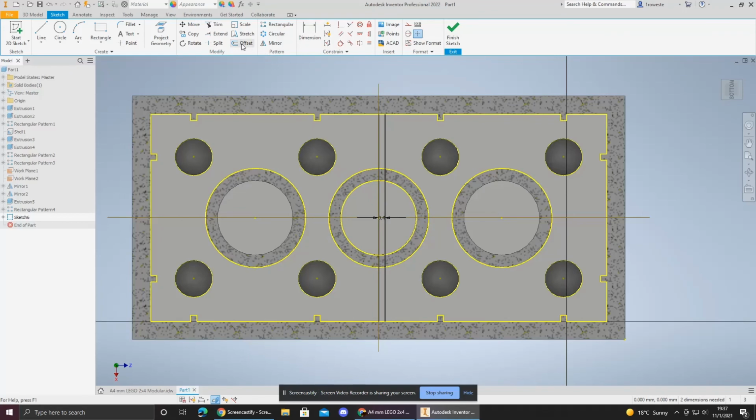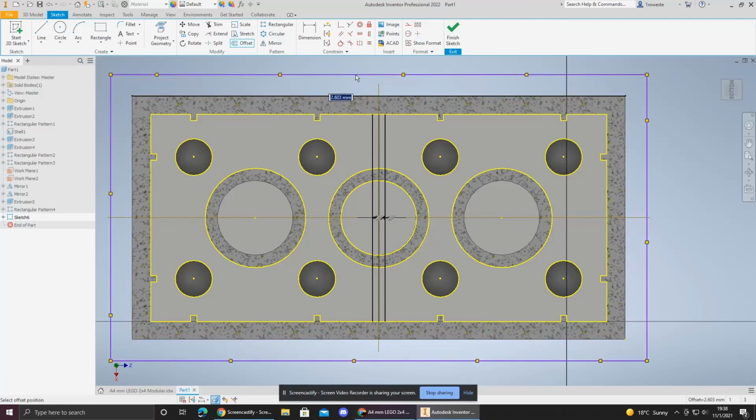Now we may offset again from the center at 0.4 millimeters, or we may offset from the first offset at 0.8 millimeters. This has created an appropriate bar, with appropriate constraints, with arguably fewer steps. Honestly, it's up to you which you would like to use. However, learning the offset tool is extremely convenient, especially when offsetting larger structures, such as, say, an entire shell, as you can see here.